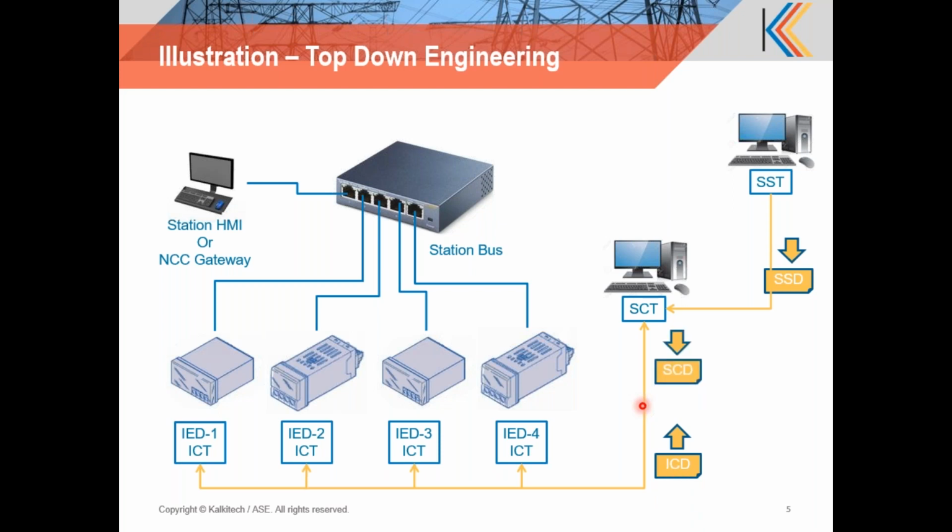The finished product is an SCD file that can be used as an input to the ICTs, where the ICTs will use an extract from the SCD file to program their respective IEDs, and the SCD can also be used to program the client HMI or the gateway.